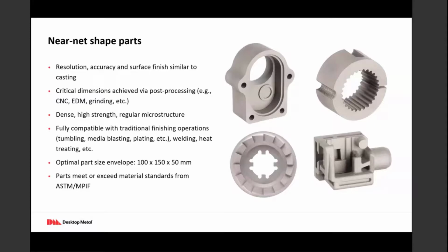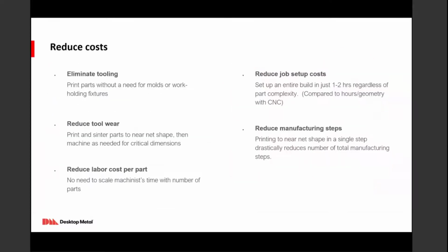And there are established standards, because this is using principles in metal injection molding. There's standards around the strength, the reliability. You can go on our website. You can check out the material data sheets. It's great that there's 60 years worth of knowledge, understanding about what MIM steels, whether it's 17-4 or other tool steels, what the behavior of those materials should be, and we meet or exceed those standards.